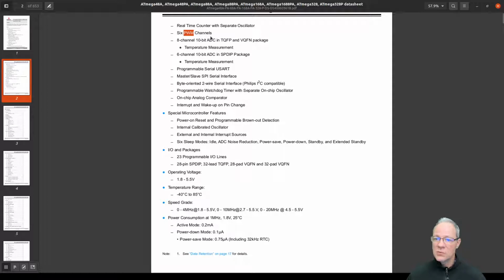Let's look at what else we have. We have the pulse width modulation channels. That's what PWM stands for. Basically, you can shape a pulse that's being sent. You can send a high for a certain amount of time, and then send a low for another amount of time, and then you repeat, right? So it's like sending 1 for some time and then sending 0 for some time, and then you repeat. And based on how long this one period is, you can do different things.